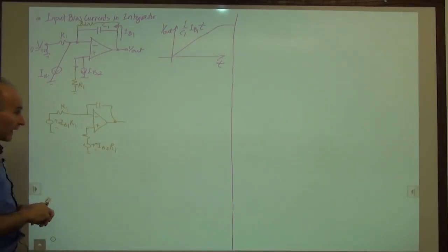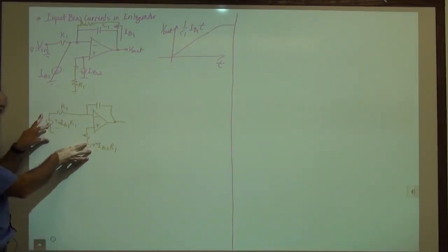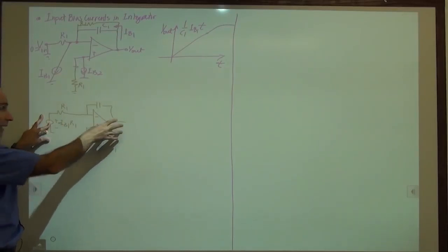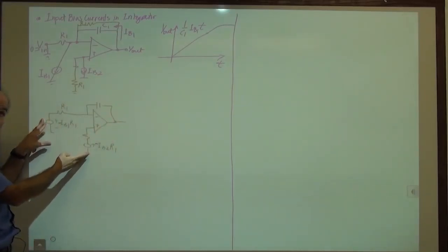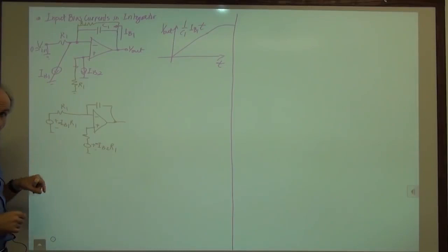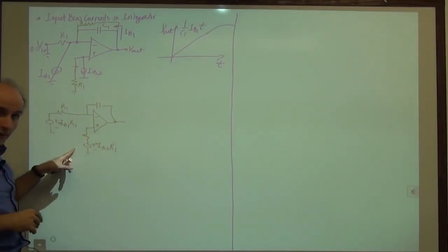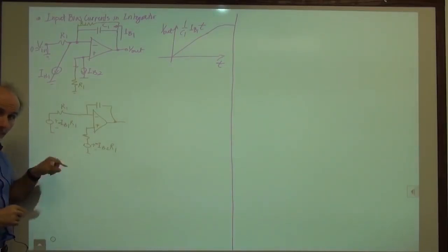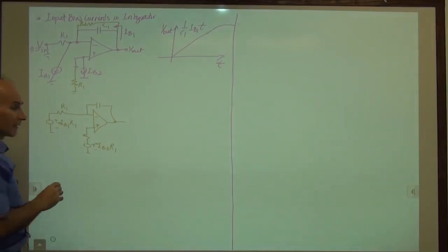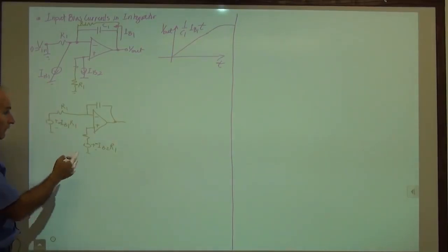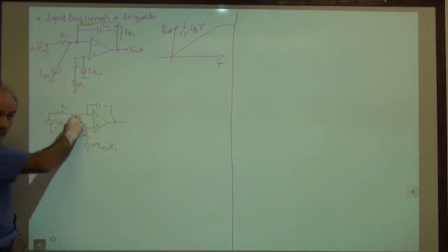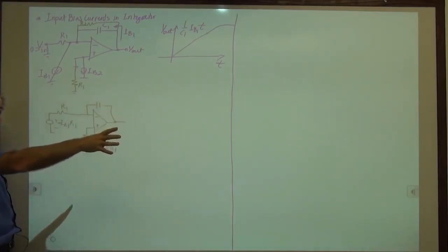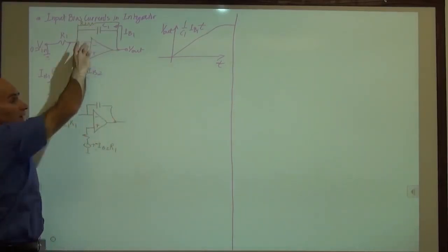So what we are thinking is that because these two voltages are equal, the integrator doesn't see any difference, so it doesn't integrate. So yes, we could try to do that, and usually we do that with bipolar op-amps. But keep in mind that if there's a slight difference between IB1 and IB2, we still integrate. So the only reliable solution is to use this resistor.